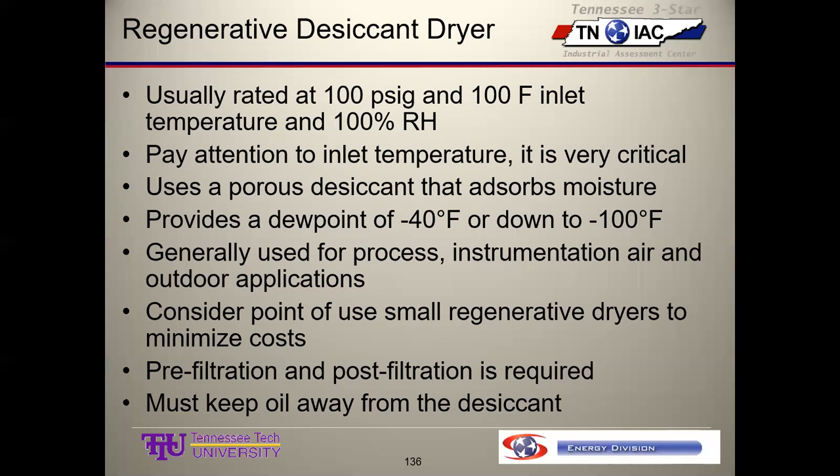So we go around and look down the aisle. I think they had 5 or 6 or something like that. I mean, it was a big system. They go, yeah, -92, -80, -70, -87. So I go, well, you guys got some dry air now. You know, there's no disputing that. But if it's way drier than it needs to be, you're wasting money. And we talked about that surprisingly long time.